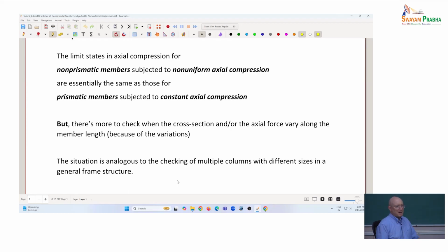From that, I get an eigenvalue. Given these axial forces placed on all the columns, the force in all those columns at buckling is the eigenvalue times that reference force. So then how would you check the strength of all those columns?